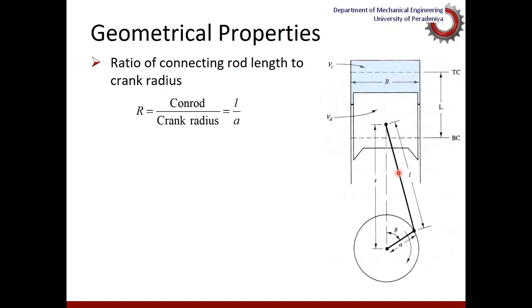And at the same time, there are a lot of rubbing components within the engine, so those rubbing components will create friction, and there are a lot of friction losses. So we want to minimize the heat losses. If you want to increase the engine efficiency, you'll have to make it close to an adiabatic process. That means you'll have to reduce the heat losses as much as possible.